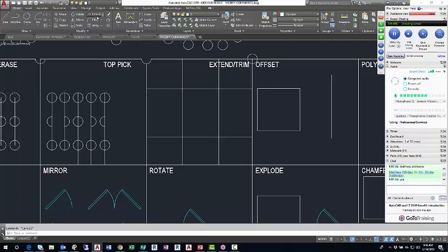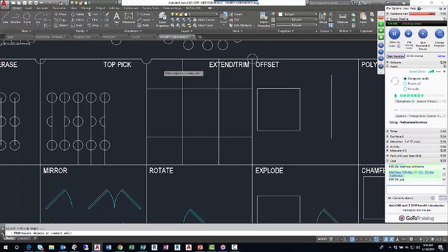So I'll go ahead and click extend, move the crosshairs into the drawing window. The command prompt is to specify, or excuse me, select. Actually, I want to use trim. Pardon me. Let me open up where trim is. Click trim. Move the crosshairs, the pick box, into the drawing window. Select objects. The objects AutoCAD wants me to select are cutting edges this time. So if I right click or hit enter, I'm telling AutoCAD everything in this drawing is a cutting edge, and then I can again cut these lines back to the point where they are.